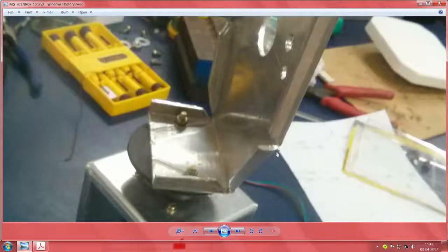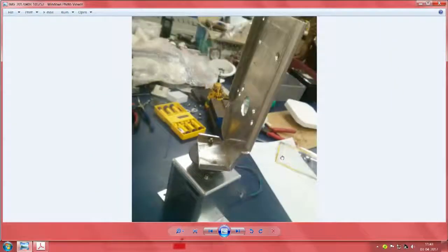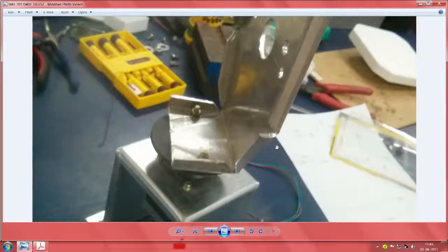This whole thing was cut out on a 90-degree notching tool, and then when we attempted to bend it, it turns out that it is not a 90-degree bend. There were some other issues with it, hence we ended up with what looked like obvious flaws in the design. These are not necessarily flaws in the design, it is just that they have all been adjusted by the constraints in production, which are specific to the machine, specific to the various conditions of bending and so on.